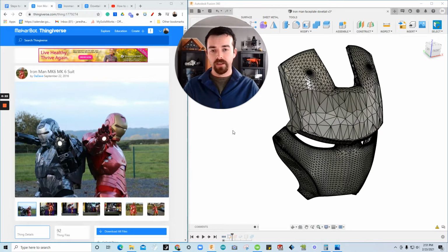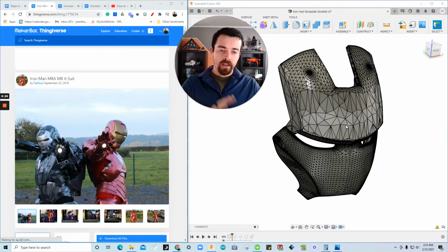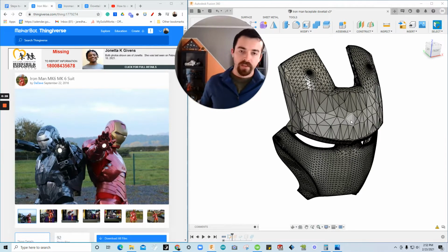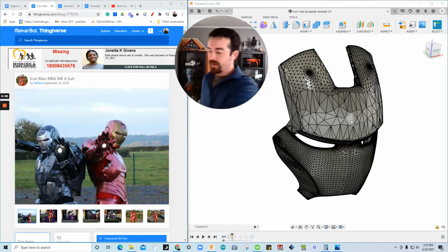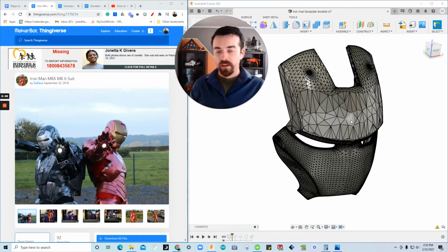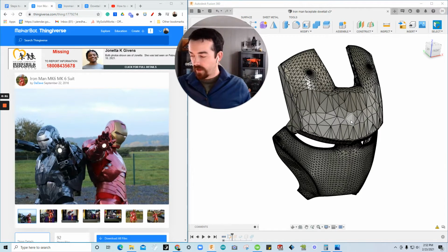So say you want to customize features such as I did back in the day for this Iron Man mask, where I was making a straight cut in the print software. It's easy, but it's kind of obvious that when I dropped this later, it broke along the line that I epoxied together. So I wanted something more complex, like a dovetail, so that the parts will snap together and then have a lot more strength once adhered. So that's what we're going to do today.